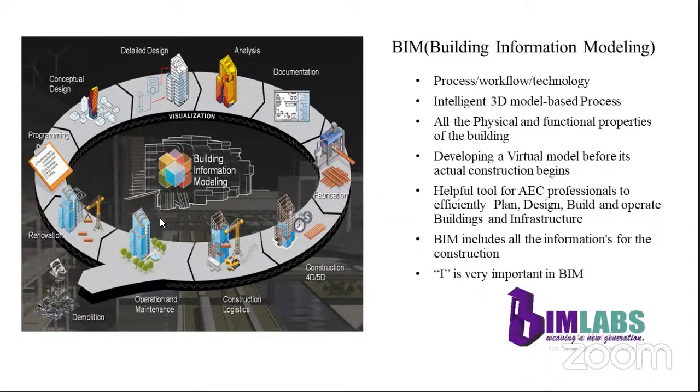For doing the structural analysis using BIM, we use software like ETABS and STAAD. By doing the structural analysis, they can assess whether the building is safe or stable. We analyze the building after applying all the possible loads coming onto the structure, like dead loads, live loads, wind loads, seismic, etc. By confirming the structural stability, we can go for the structural modeling. Like this, mechanical, electrical and plumbing engineers can make their own models.